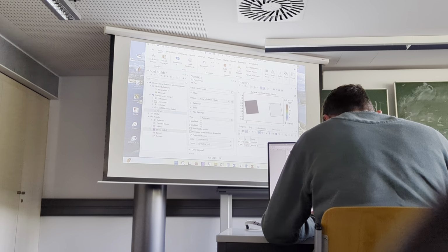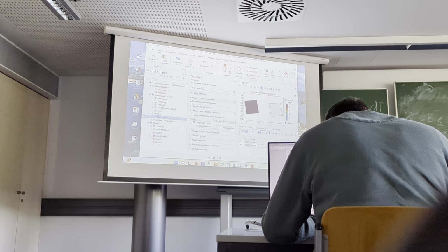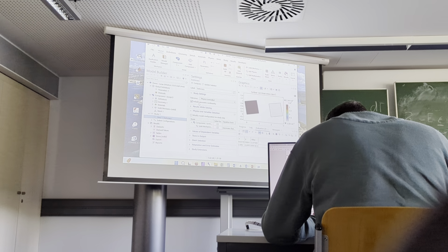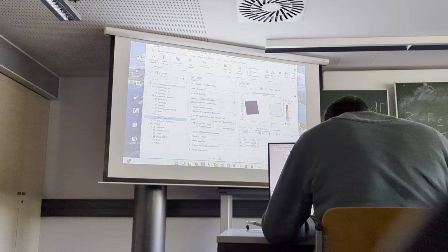And that resulted from a setup. Maybe first of all, in study, that's where you control the solution. Stationary. Here is the mark. If you enable this, then the geometric nonlinearity is included. So that's where you have to know where you have to do something. Basically, that's it. The other thing I did here was just for illustration. If you think the displacement is so large that you should use the exact definition of strain, you just make the mark. Make sure that there is a mark.